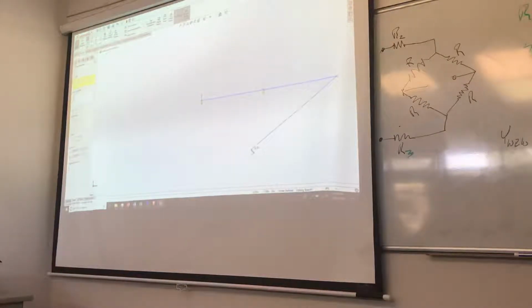So I've got a line that I'm drawing. I'm going to dimension the line. I'm going to say 144. And then I'm going to click on the line here and 0 on the line. Okay. And I have a 144-inch line, and now I want to make that a beam. Okay. And in SolidWorks,